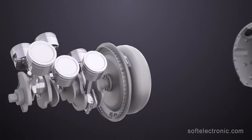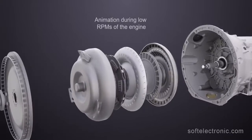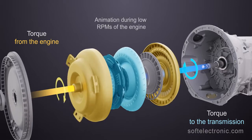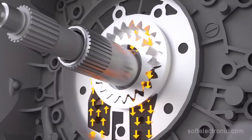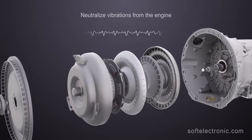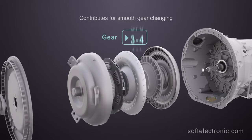The torque converter is a fluid coupling between the engine and the transmission. It has several main functions. It increases the torque from the engine to the transmission when the vehicle is moving. When driving off, the torque is increased the most. It operates the oil pump in the gearbox. It helps neutralize fluctuations and vibrations from the engine to the transmission. It contributes to smooth gear changing.